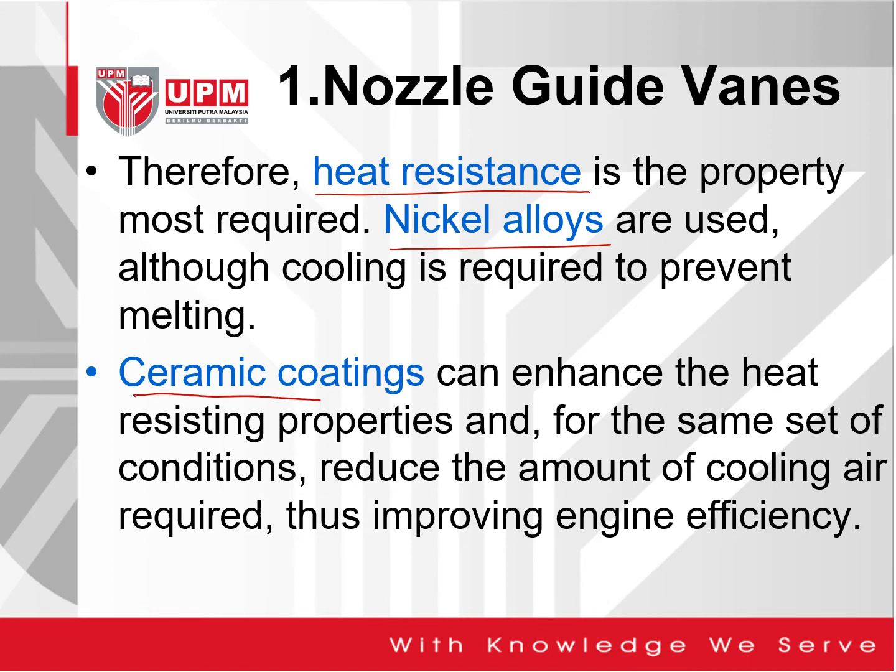And in some cases, ceramic coatings are also being embedded or coated on the nozzle guide vanes to enhance the heat resisting properties. For the same set of conditions, this reduces the amount of cooling air required, thus improving engine efficiency.